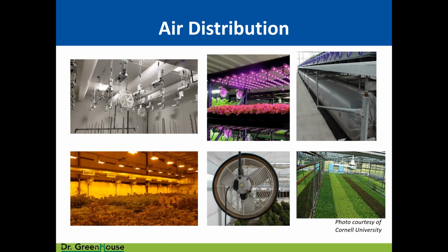If you're in a vertical farm, this is a very small version, but a lot of you are using fans like this hanging from the racks to maintain the momentum of air across the plants. In greenhouses, you see horizontal airflow fans a lot. That's really good for mixing air, especially in a heating condition, so you don't get stagnant pockets of air. You see air tubes below benches, above, like this.